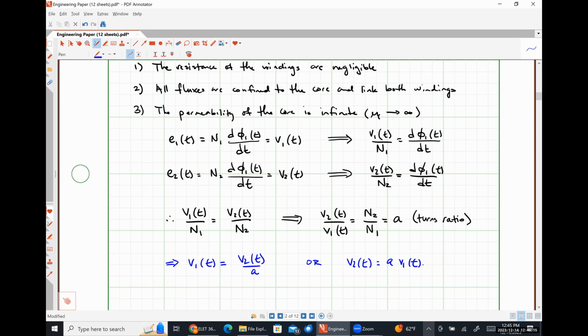Is there anything that's forcing us, if we're putting a transformer in a circuit, is there anything specifically that forces us to connect one coil to the high voltage side and the other coil to the other side? Not at all. A transformer is completely and utterly interchangeable. So it's up to us to connect things correctly to get the desired response. Do we want to step the voltage up or not? Kind of thing.